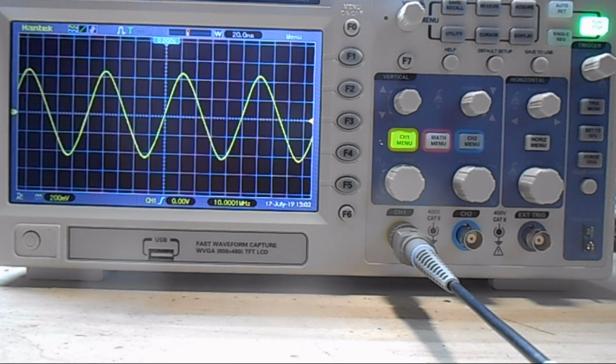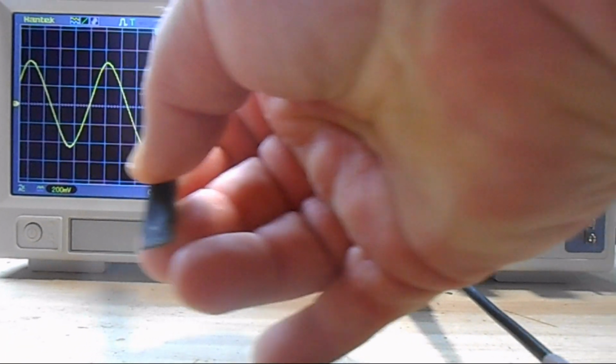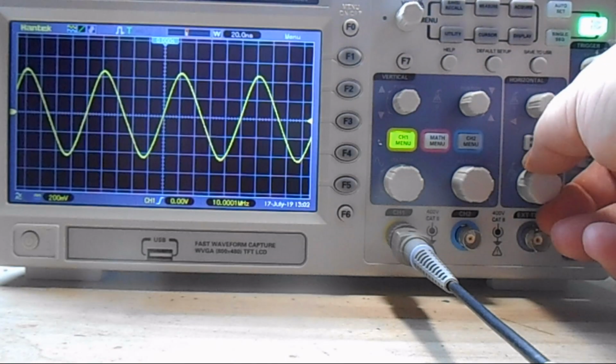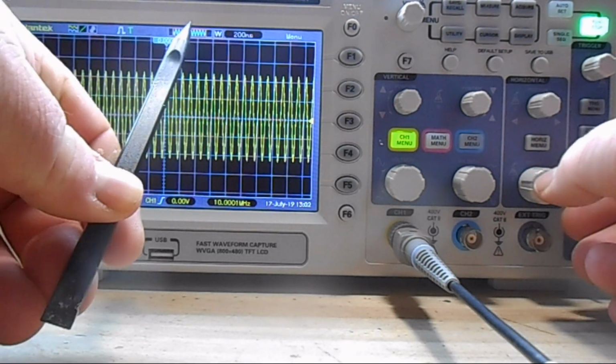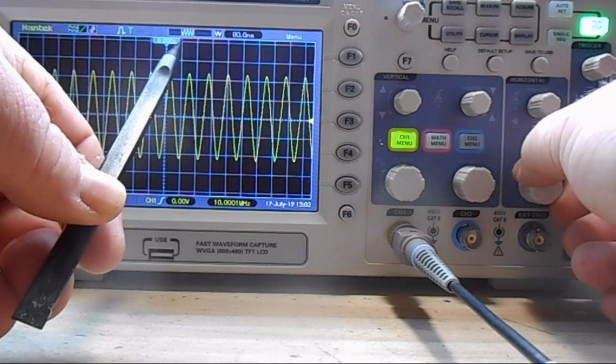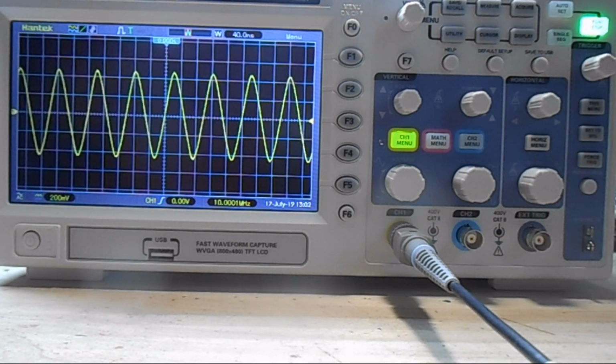And that goes hand in hand with record length. It might also be called deep memory, but it's basically record length. The larger the memory, the greater the record length, and the more time a signal can be captured. Does that make sense? Having a larger record length allows our scope to capture more. You see how tiny this little red box up here is, showing us how much of our signal is actually captured? Now see how it gets larger? That's to do with record length. So the larger the record length, the more of the signal you can capture.